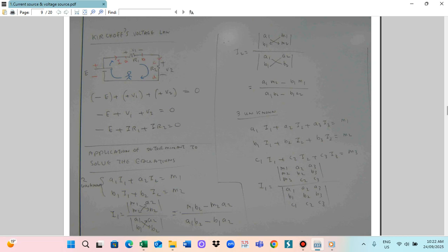Okay, you have to put the positive and negative signs. For the battery, the longer terminal represents positive and the shorter terminal represents negative. When the current flows, the entry side will be positive and the exit side negative. For resistor R1, the side where current enters is positive and the other side is negative. Similarly for resistor R2, the current entry side is positive and the other side is negative. This way you can label the points A, B, C, D.